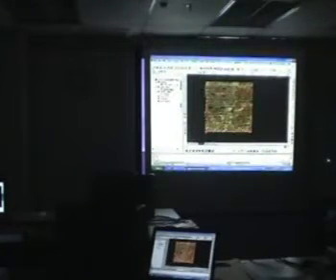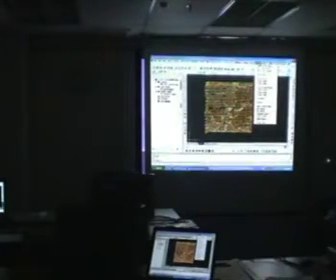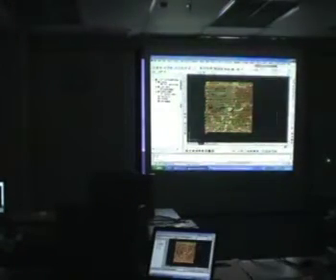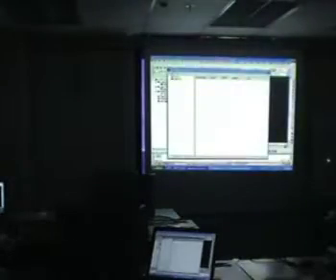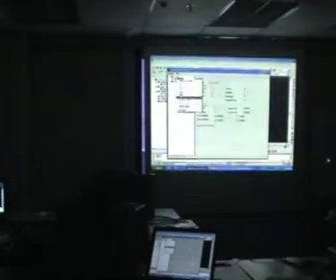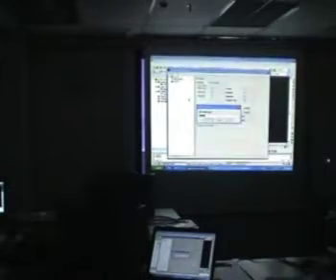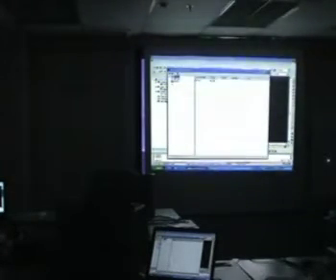So now we've got our points, and I'm going to run the triangulation now so you can see this in 3D. I'm going to go to Terrain, go to Terrain Model Explorer, and I'm going to create a new surface. So each surface is basically like a new level, for example. Let's say I call this OGL, original ground level. So this indicates this is going to be the original level, the existing surface which the project looks like.